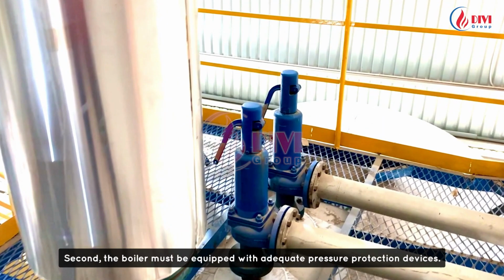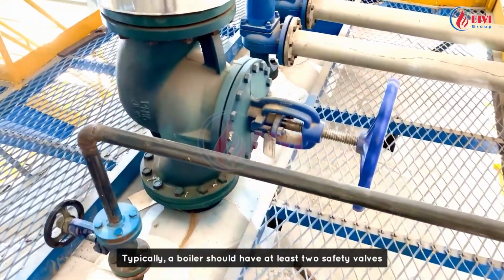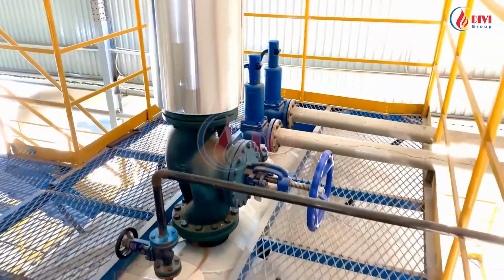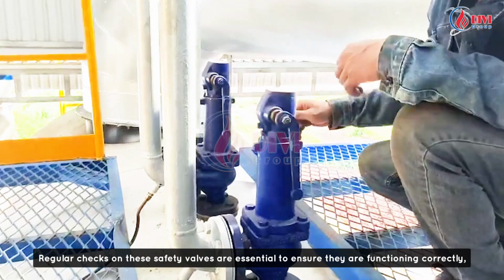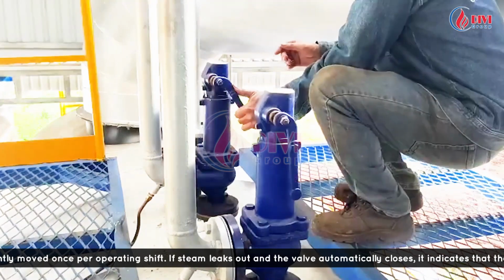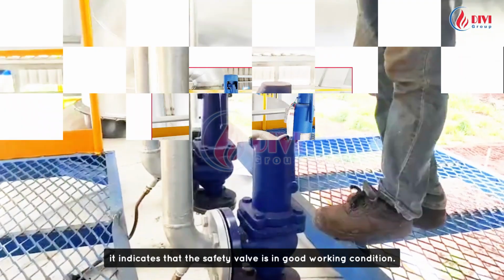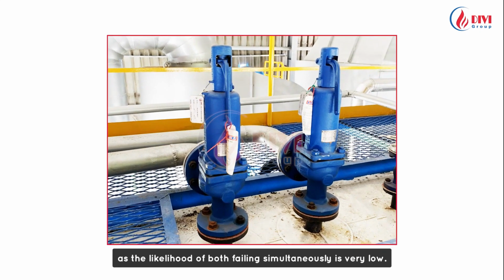Second, the boiler must be equipped with adequate pressure protection devices. Typically, a boiler should have at least 2 safety valves. These valves automatically release steam when the pressure inside the boiler reaches a certain limit. Regular checks on these safety valves are essential to ensure they are functioning correctly, often by manually testing the lever. Ideally, the safety valve lever should be lightly moved once per operating shift. If steam leaks out and the valve automatically closes, it indicates that the safety valve is in good working condition. 2 safety valves ensure high reliability, as the likelihood of both failing simultaneously is very low.